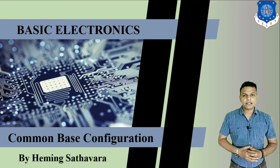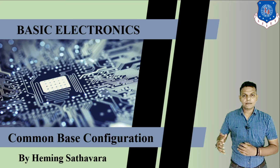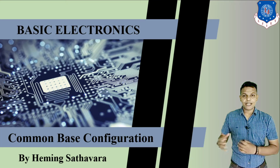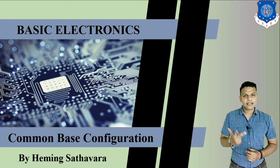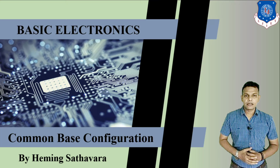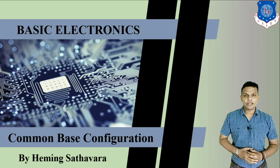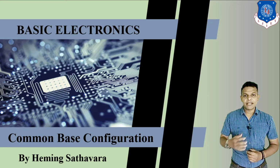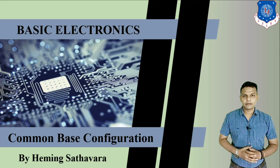Common configuration means that if you take one terminal as common, that becomes a common configuration. As we know, there are three different terminals in a transistor: emitter, base and collector. When we make one particular terminal common, it is known as a common configuration. So in today's lecture we are going to do the common base configuration, that means the base terminal is going to be grounded, or we can say common.